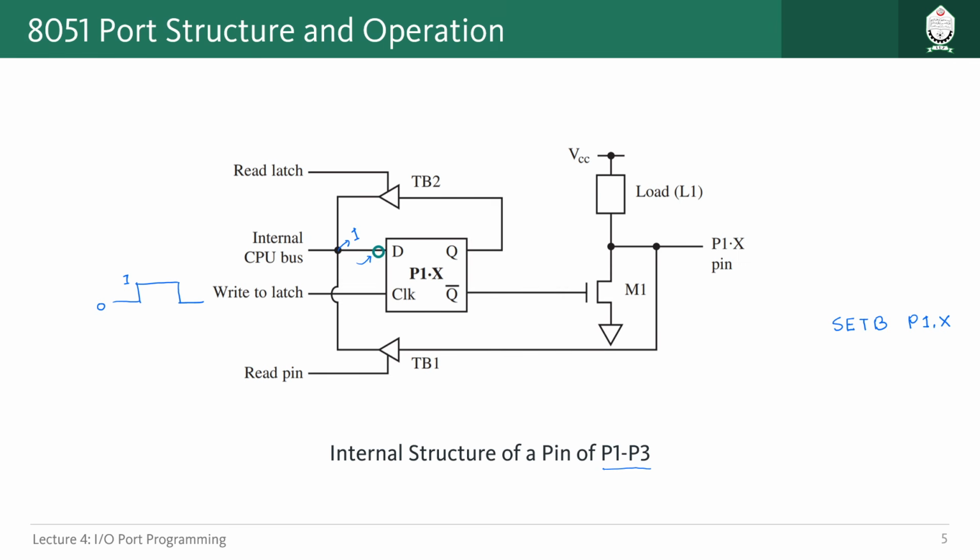And this one, I think you already know about. This is called a tri-state buffer. You learned that in your third semester maybe. A tri-state buffer works on the mechanism that if you have 1 or 0 at the input, nothing will happen at the output as long as you don't give any enable signal through this particular pin.